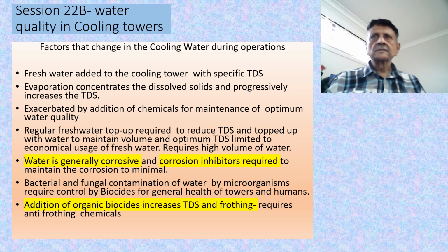As the cooling tower operates and continues to operate, the heat that is transferred into the water evaporates. The water evaporates and it concentrates as the dissolved solids from the water accumulate, and this will progressively increase the TDS. There is also a decrease in volume because of evaporation, and it is necessary to add water to top up the water to maintain the same volume.